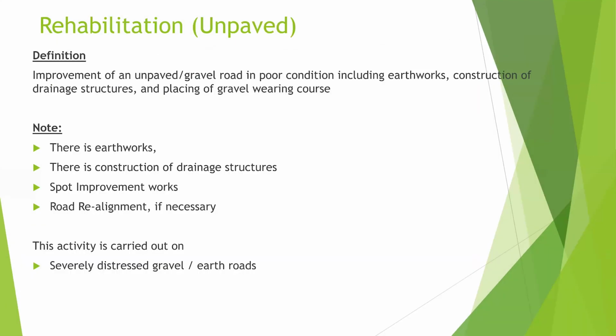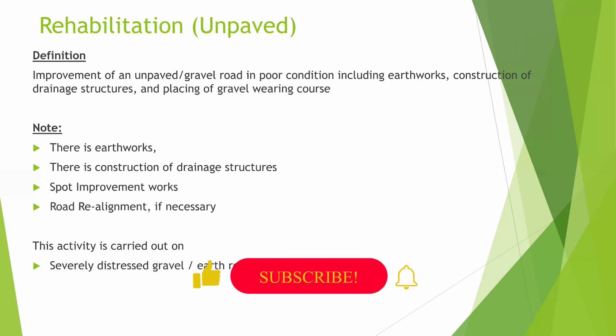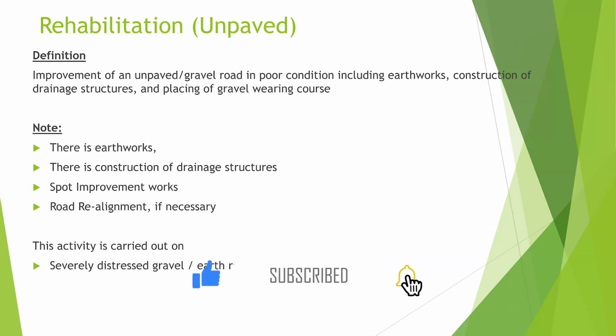The next activity on unpaved routes is rehabilitation on unpaved. Now, we talked about rehabilitation on a paved route earlier, and now we are talking about rehabilitation on unpaved. The additional activities here include earthworks, drainage works, and then in addition to that, the regraveling, that is the gravel wearing course.